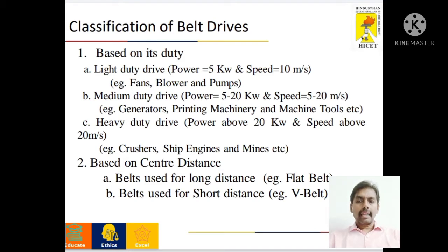Based on duty, the first one is light duty drive, second one is medium duty drive, and third one is heavy duty drive. In the light duty drive, power is up to 5 kilowatt and speed up to 10 meter per second. For example, you can use this in pumps, blowers and fans.